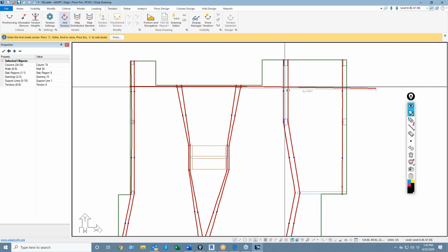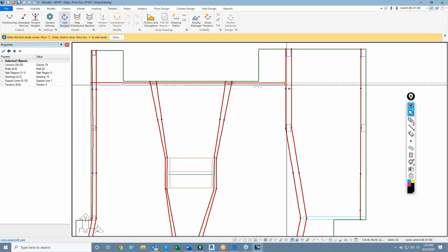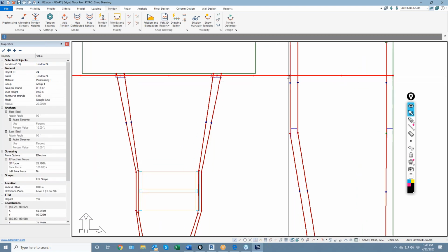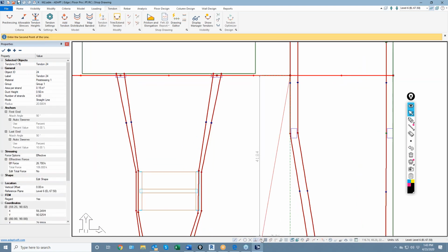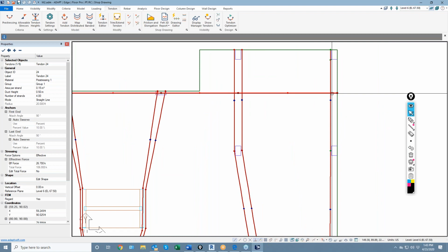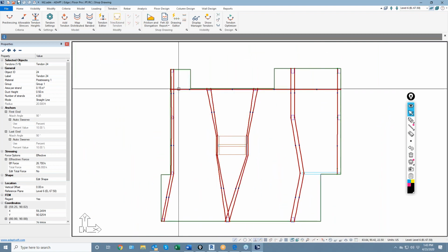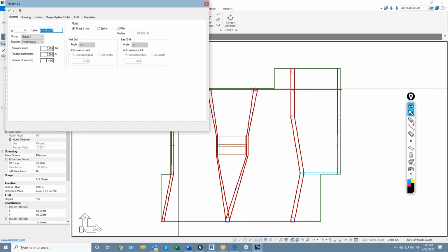calculated if I just take the area of a unit strip. It could be 1 foot, it could be 2 feet, 3 feet, whatever you determine as the unit spacing of the cable. That's really your decision. The ACI code says they have to be spaced no more than 8 times the slab thickness, so that might be a limit, but here we'll just say every 4 feet. So this cable, we're going to say we need 2 cables every 4 feet, 2 tendons.